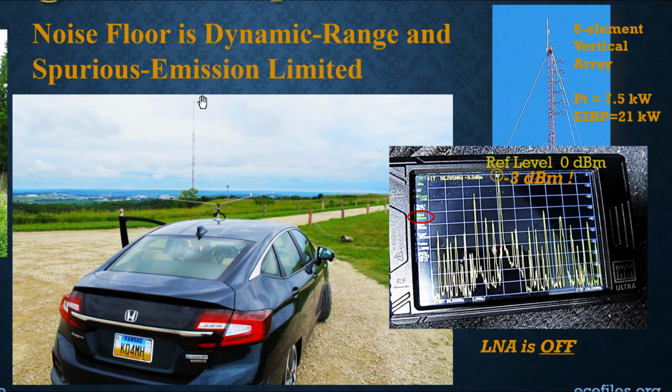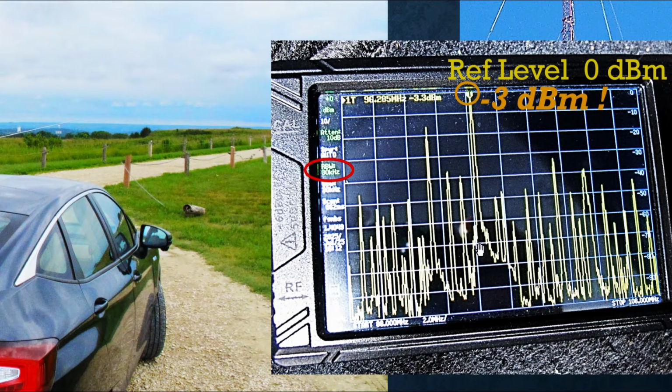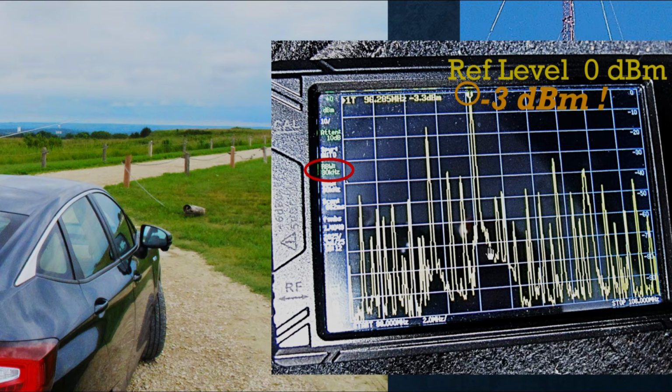And radio transmitters are not perfect. They have their own limitations. And one is that if they're pumping out signal at a particular frequency, there is what's called spurious emission at offsets from that frequency. My guess is this tower completely satisfies FCC rules, but those rules aren't going to specify that you have to have absolutely no emissions at say 200 or 400 kilohertz offset. So it looks good here, but in this region down at the bottom, I think those are spurious emissions.